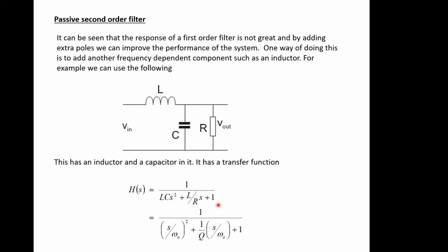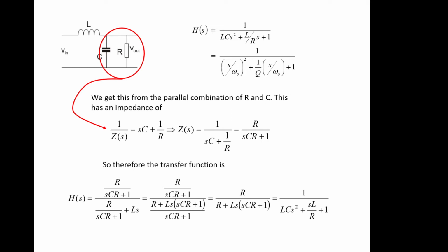And we can match this to the standard second order response with omega c and everything as being in this form. So we would be defining a Q factor, which we'll see comes down to peakiness, as being this. But this is a well-known expression. It's a standard form for a second order system, and there's lots of standard results that come from this. So we will try and squash any second order response into this type of form, and then we can match components, and then we can just use the standard solutions on it. So how do we get to that?